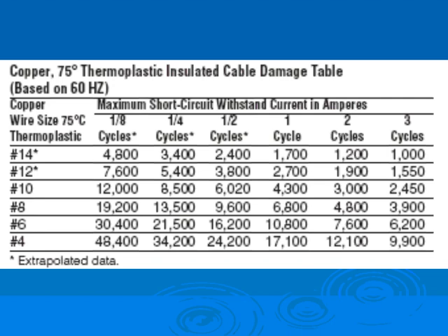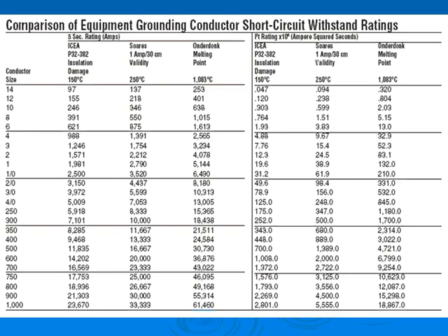So in the low voltage world, and that's number 14, of course, you have all these numbers. These are called the damage curve for conductors, depending upon the installation that they have and the installation rating. This one, guys, shows comparing the 5 cycles for different types of conductors. What is the equivalent grounded conductor short circuit withstand?